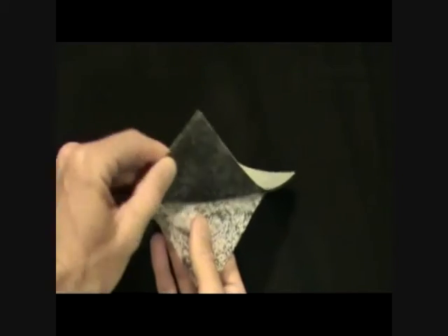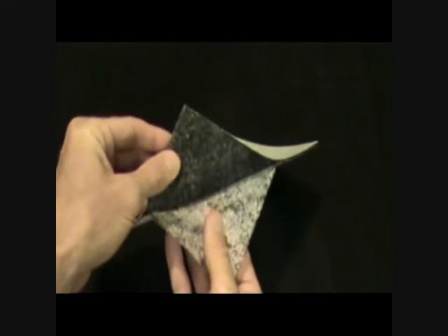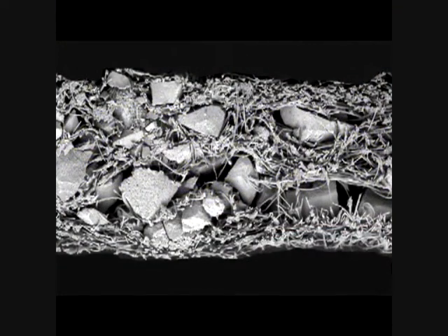We mentioned before the importance of maintaining active surface area on the adsorbent. And this is really where the polymesh adsorptive media shines brightest, through the patented use of a fibrous binder matrix. The polymesh media maximizes available surface area, as can be seen in this SEM image. As we discussed earlier, active area plays a key role in performance. And notice how the use of a fiber binder maximizes the useful area of the adsorbent. Not only that, but the use of a fiber binder enhances diffusion capture by creating a tortuous path that the adsorbates must navigate during their travel through the polymesh matrix.